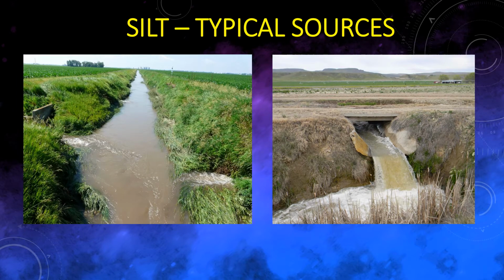Another source of solids in irrigation water, particularly with open delivery systems, is runoff from fields. Typically, you'll have interceptor canals, or you'll go back to a canal downstream that may go to other farms, and you can obviously see the silt that's present in this water that either plagues current filter technology or can't be easily removed without settling basins or other types of overshot structures, and even those aren't 100% effective.